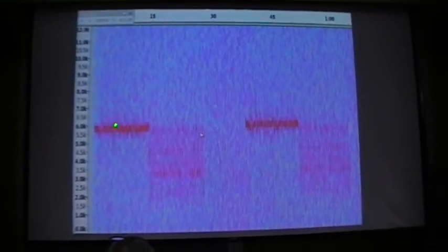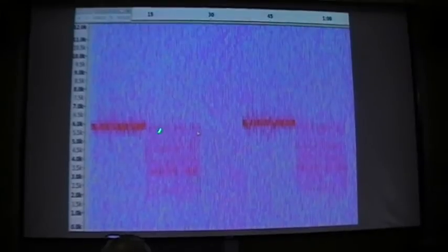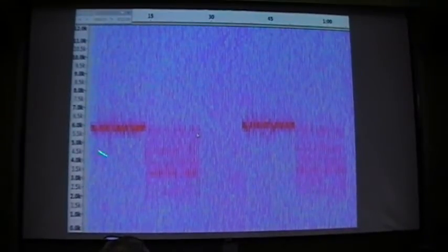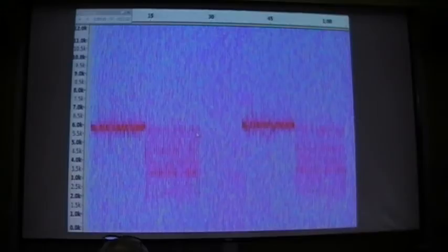Now this plot shows why. This is a spectrogram, so we've got time going across here. And what we're doing is alternating FreeDV 2400A with the FM signal. Now the FreeDV 2400A signal is much narrower. So all the power we've got available from the transmitter is put into a smaller RF bandwidth, which means it has a much better job of picking it up. But the FM is spread over a much wider area, so it's sucking up a lot more noise at the same time, and that impacts on how well we can do in demodulating it. So that's 2400A, 2400A, FM, FM. So that's just a plot of the signal at the input to the demodulator.